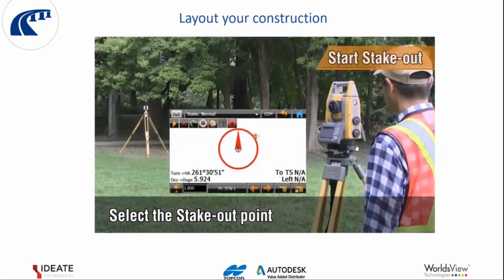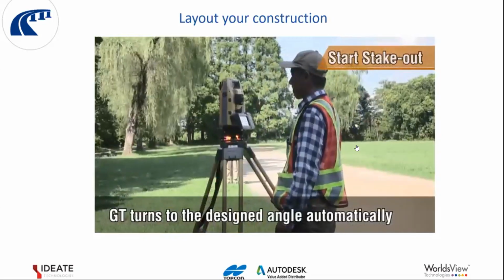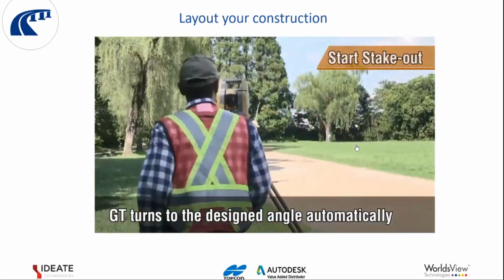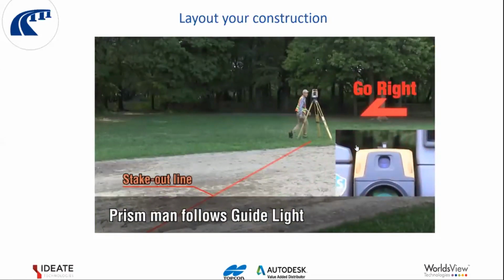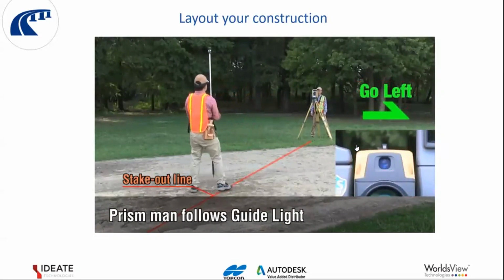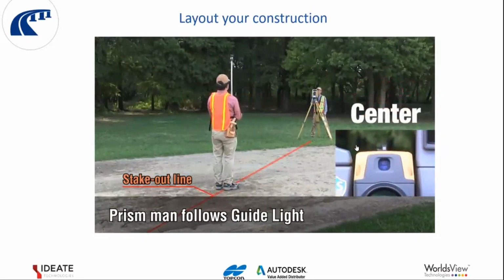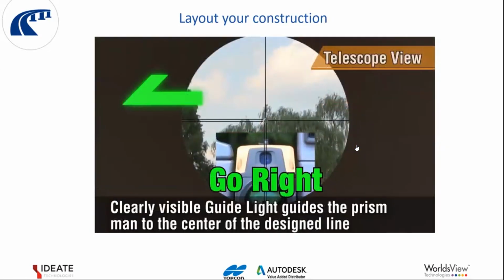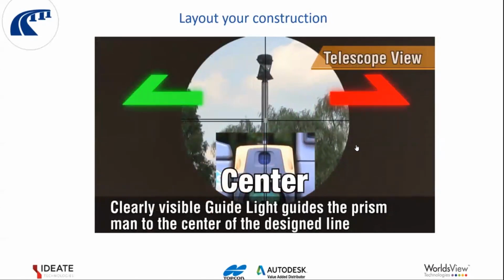the machine in the field turns automatically to the right angle. So without trying to reach the angle, it does that automatically, and it helps you with the lights. The red lights mean go right, and the green one means go left, and the yellow one means the center, stay in the center. So clearly visible guidelines guide the prism man to the center of the design line.